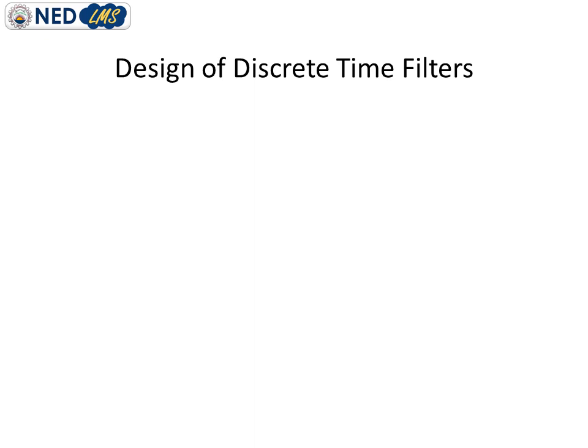So instead of just accepting a given set of FIR filter coefficients and analyzing the frequency response, we are more interested to reverse the process and design our own FIR filter. That FIR filter may be of any kind. For example, it may behave as a low pass filter, or a high pass filter, or maybe a band pass filter or band stop filter. So any kind of filter can be designed.